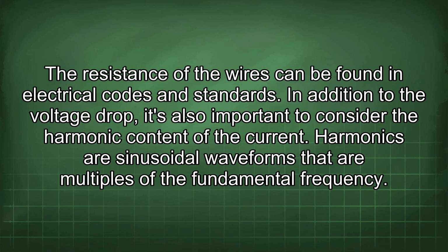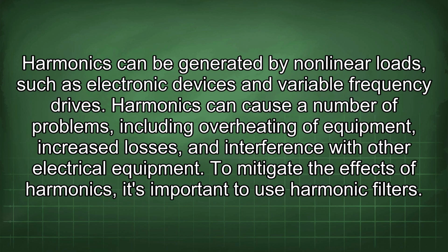In addition to the voltage drop, it's also important to consider the harmonic content of the current. Harmonics are sinusoidal waveforms that are multiples of the fundamental frequency. Harmonics can be generated by nonlinear loads such as electronic devices and variable frequency drives. Harmonics can cause a number of problems, including overheating of equipment, increased losses, and interference with other electrical equipment.